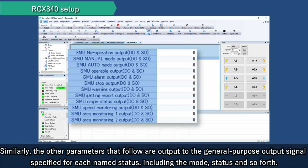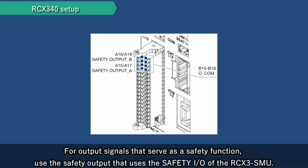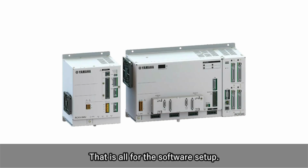Similarly, the other parameters that follow are output to the general purpose output signal specified for each named status, including the mode, status and so forth. For output signals that serve as a safety function, use the safety output that uses the safety I/O of the RCX3-SMU. That is all for the software setup.